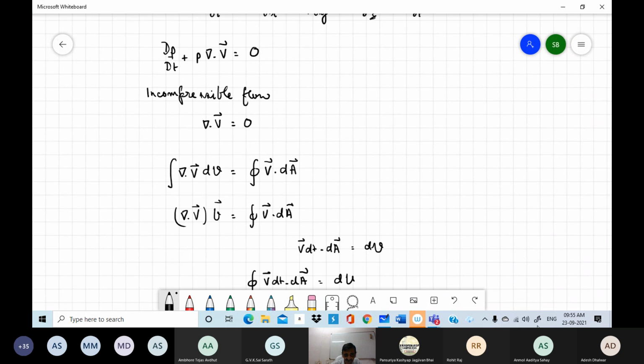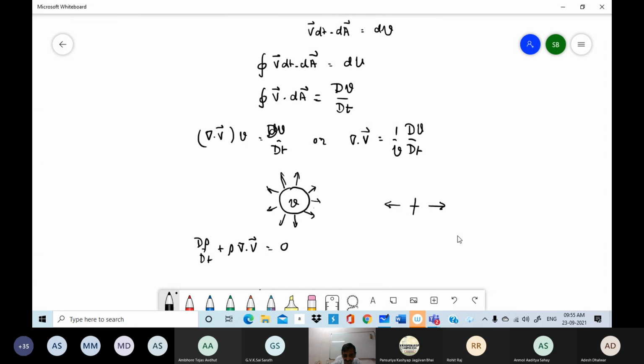So what it says is, if I have a field with a positive divergence, that means its volume is increasing. So correspondingly, if I follow the material element, where if I bring this to this side, it will be a negative quantity. So rho must decrease. So if volume is increasing, the density must decrease in order to conserve mass. So that is what this represents physically.